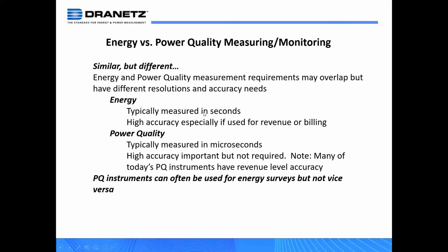They would purchase or acquire instrumentation whose resolution is in seconds, and then will be severely disappointed when they try to use it in PQ applications, when they're trying to detect these microsecond power quality events. And so the best scenario here is that today's instruments having the ability to do power quality and energy would typically have resolutions in the microseconds.